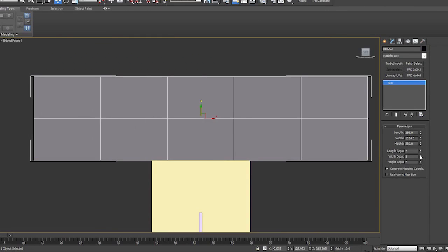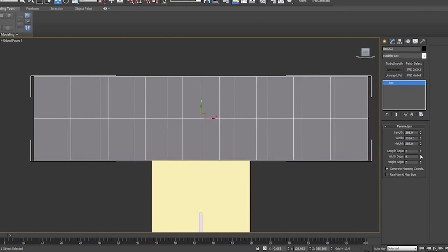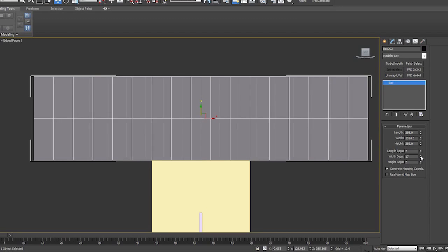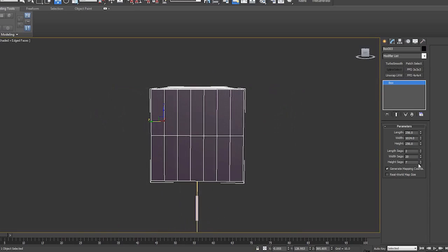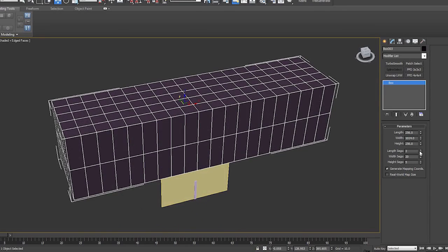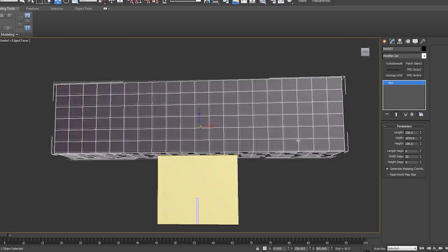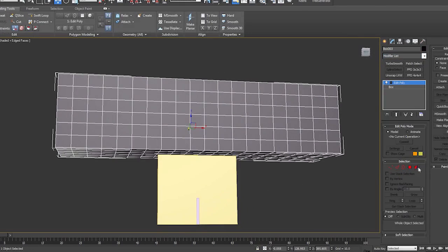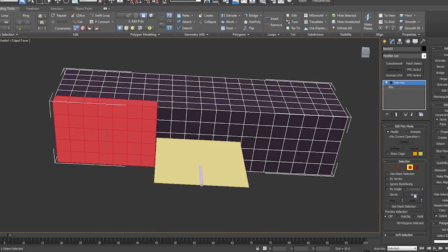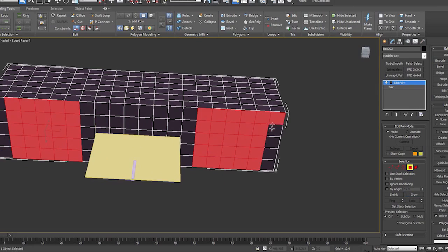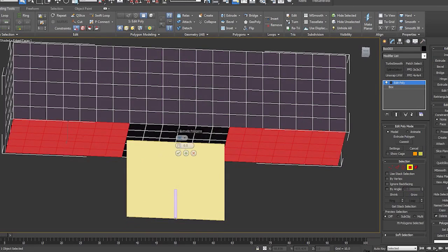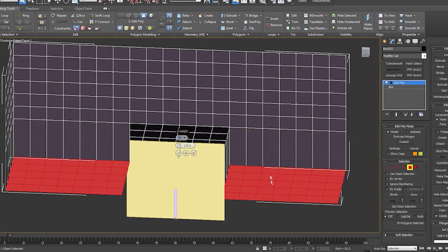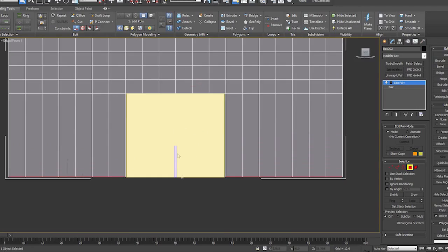One thing that's important when you're taking a model from 3DS into a high poly sculpting application like Mudbox is that you're modeling in quads and that it's going to subdivide nicely when you get it in there, so that way you don't have any weird stretching. Just dropping an edit poly modifier on top of it there, so that way I can always go back and take those out later if I want to. I'm actually going to be using a different program to reduce the amount of polygons instead of going back to edit it, but that only works on certain kinds of models.